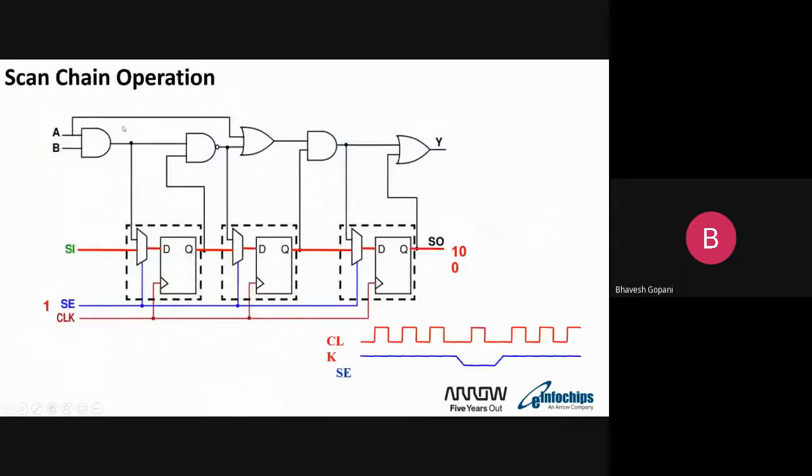Let's say there is an OR gate, and this input is controlled by this flop, but another input is constrained, or sorry, tied somewhere in the design. Tied in the sense that it is driven by some test mode, because test mode is always one during testing. Otherwise, if it is zero, the circuit would be in functional mode.